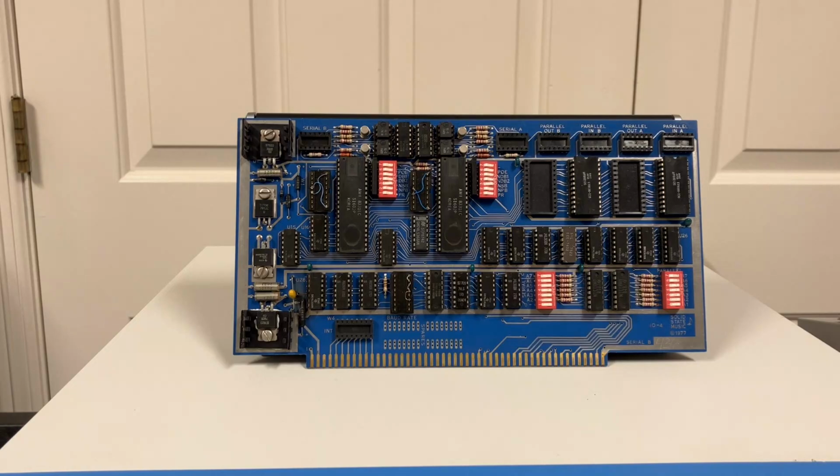So in that last video, I created a link to a file I made that was a list of serial boards from back in the day that I thought you might be able to use in order to create your own cassette interface, in addition to the Solid State Music IO4 board that we demonstrated in the video. Since then, I've been able to actually test several of those boards and prove that they work. I've found some that were very easy, some that required a couple of minor mods, and others that I could just write off the list. They're not going to work. And so that's what we're going to do in this video. We're going to take a look at some of these additional boards I've found that can be used as the serial interface board in a drop-in equivalent for the Altair Cassette Interface.